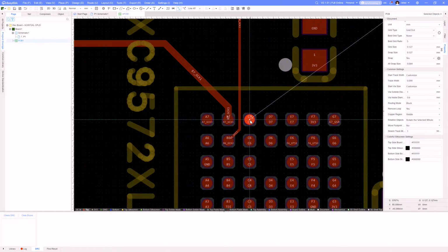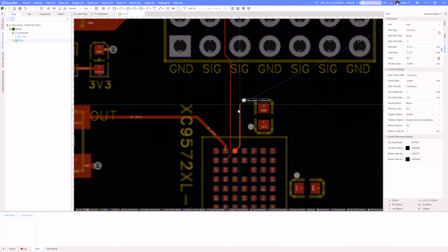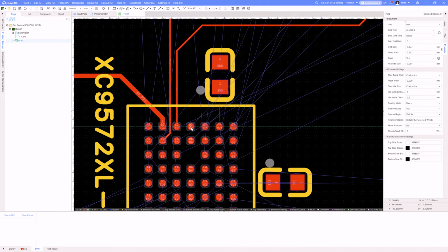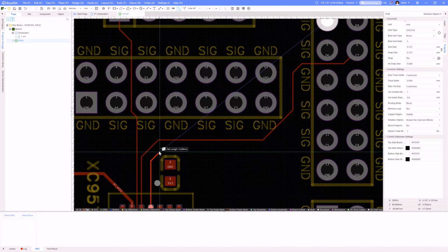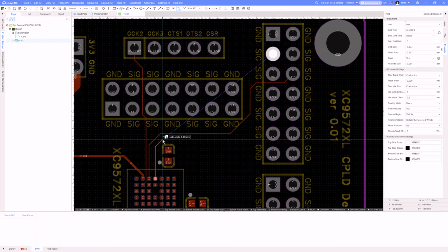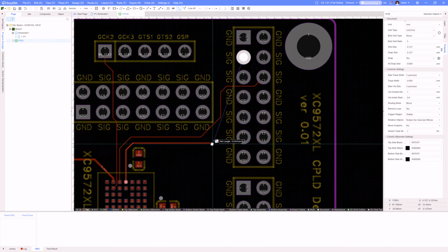So I'm going to just start doing this. I'm going to do a wire, and I'm doing a 0.1 millimeter for the size of that. And I just need to get all of this routed out. And then I'll just continue this process. And normally with these BGAs, now I'm not super experienced at this, but I'm slowly getting better at it. But here now, let's see, I've been trying to get the outer 2 rows of balls connected first.